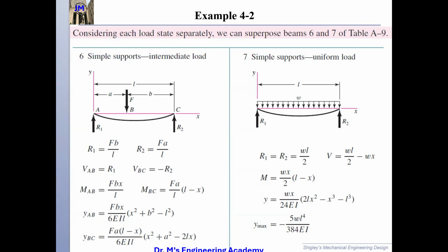Whenever you see a concentrated force, you are supposed to differentiate these two segments. Okay? Because physically speaking, the concentrated force is a singular point. You need to differentiate them definitely. For point B, because point B belongs to this interval and also belongs to this interval, if we use either of these equations, you are supposed to have the same identical result.